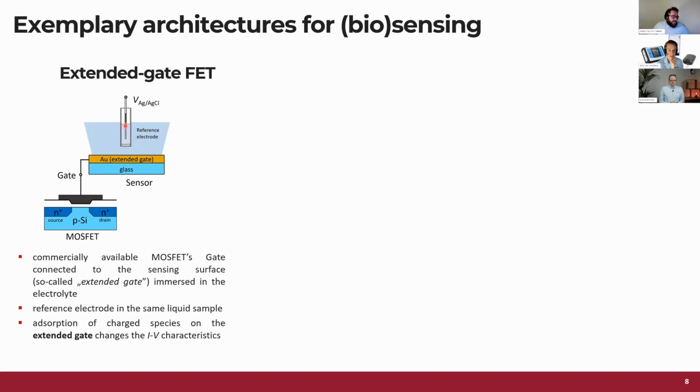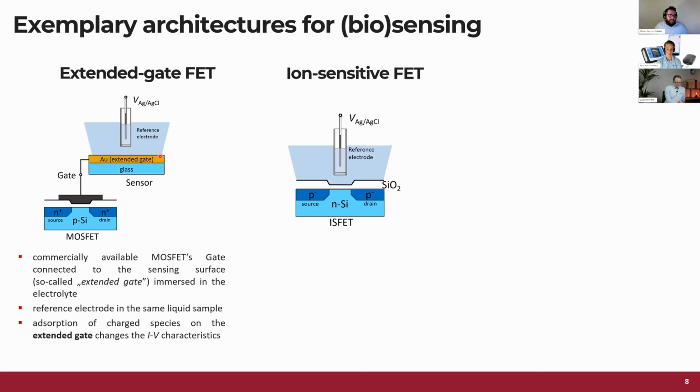The adsorption of charged species does not affect the reference electrode, because there is a FET. But whatever adsorbs on this extended gate adds to the surface potential, and that adds to the IV characteristics of the MOSFET itself.